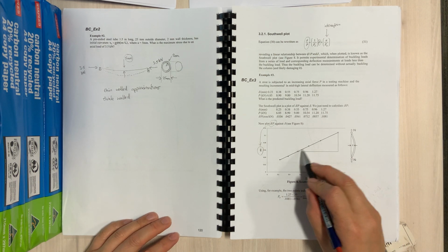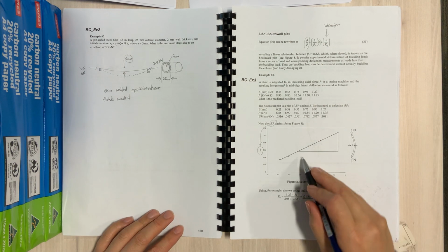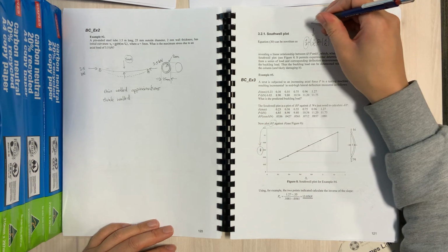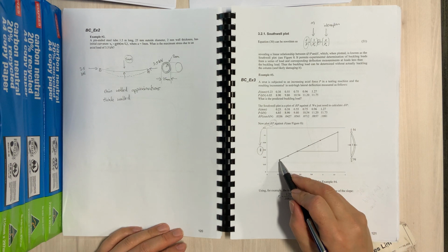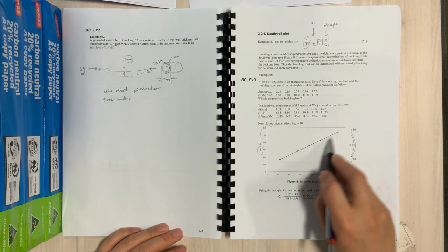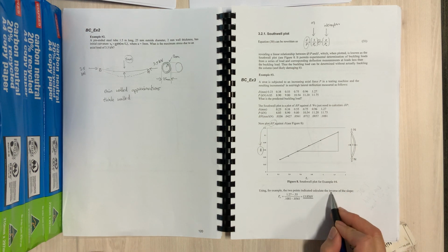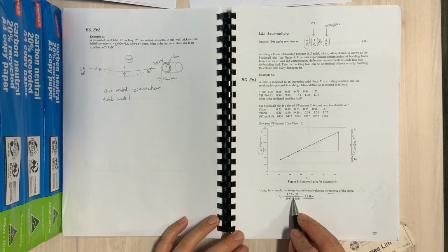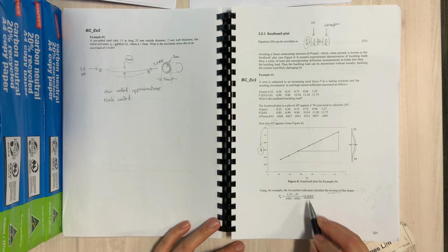And then with these data points, you can see they don't exactly line up, but you can draw a line of best fit through them. Once you've got that, you can work out the gradient of that. So that would become, from your Y equals mx plus c, the gradient m. So you draw your line, work out the gradient between any 2 points of your line. So work out the gradient m, and then PCR becomes the inverse of the slope. So you can calculate that just by doing the reverse, and then from there you work out that from your experimental test, or your non-destructive test, that PCR is 13.85.